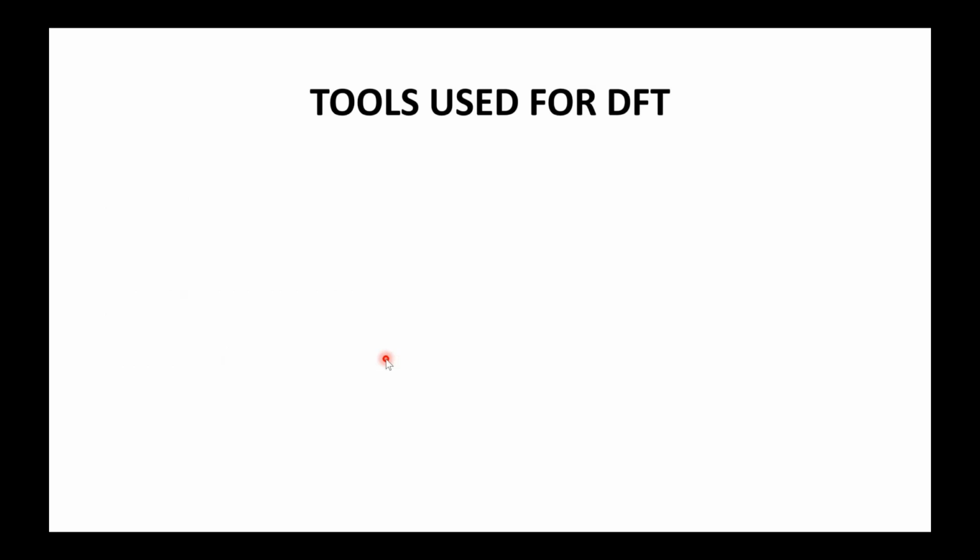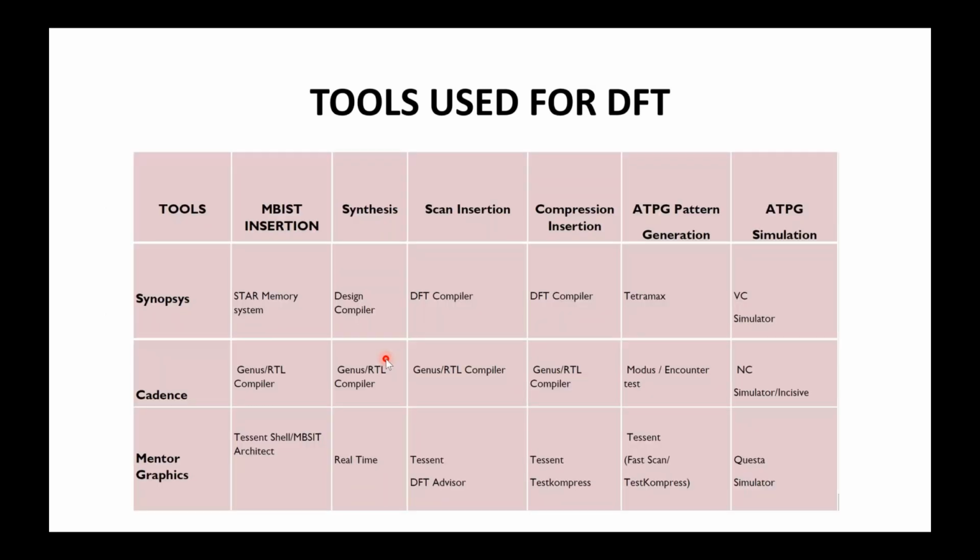These are the tools used for DFT in the industry. In our institute, we will be using Mentor Graphics tools. For MBIST insertion, we will use Tessent MBIST. For scan insertion, we will use Tessent DFT Advisor, also called Tessent Scan. For compression, we will use Tessent TestCompress.